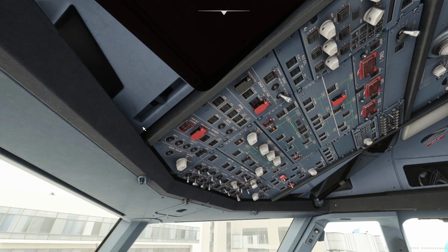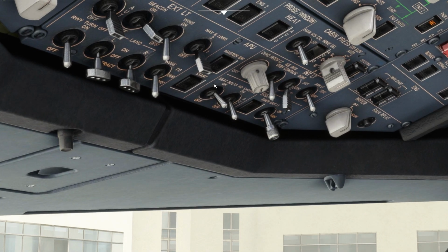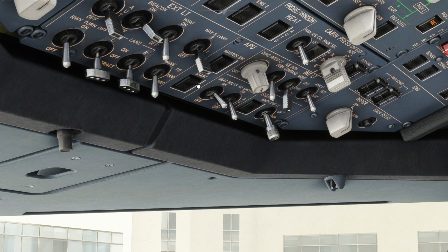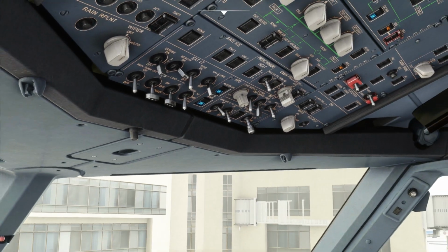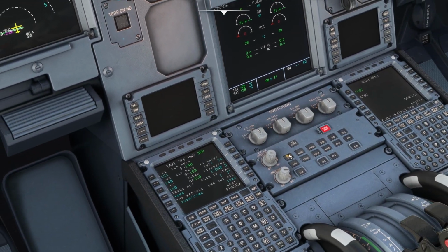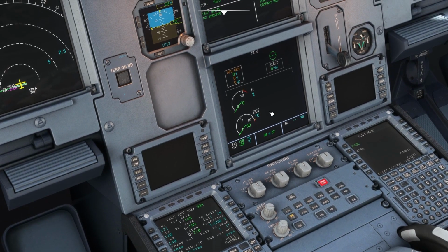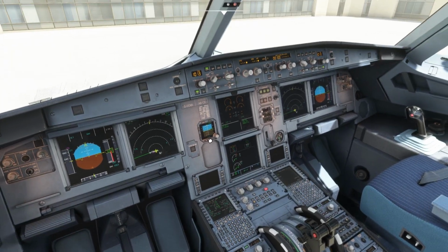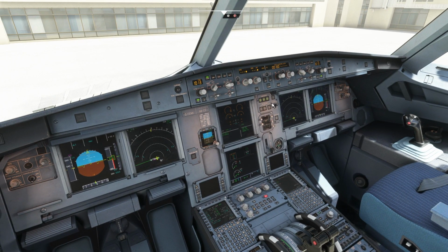Right now, let's go to this option, the master switch for the APU, and then the start. I will first press this button, wait for almost 2-3 seconds, and then I will start it. The moment I do it, you will see over here in the ECAM, if you select the APU option, the APU startup indicator will come. In order to save time, till the time APU is up, I can set the altitude 25,000 feet over here.